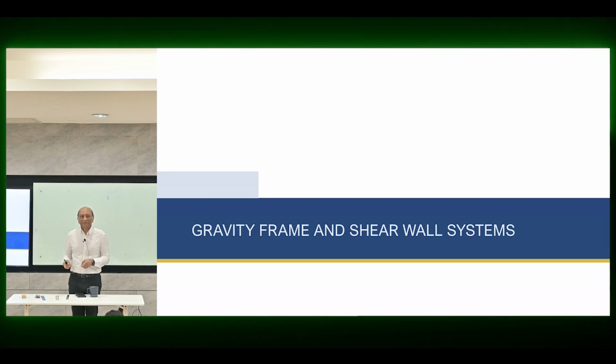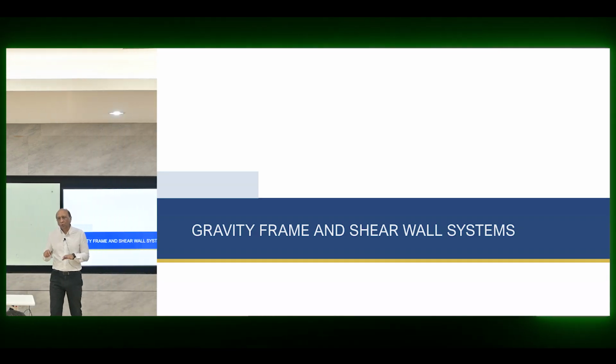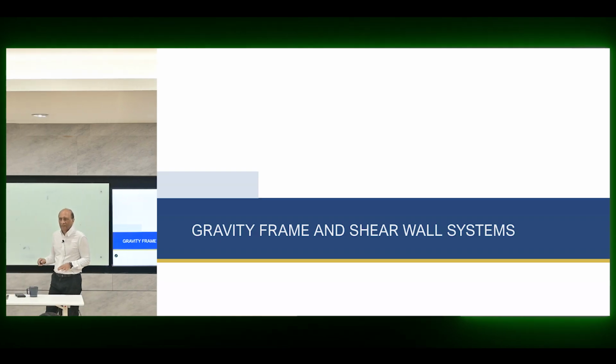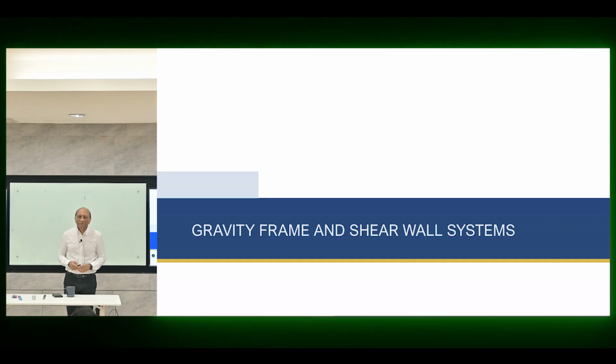And if I do that, then I can just use a flat plate for gravity load only. So the frame or the columns and the floor only carry gravity load, do not assist the shear walls, have no coupling effect, and the walls alone as cantilevers carry the entire lateral load. So that's another option, and that is a very good option.